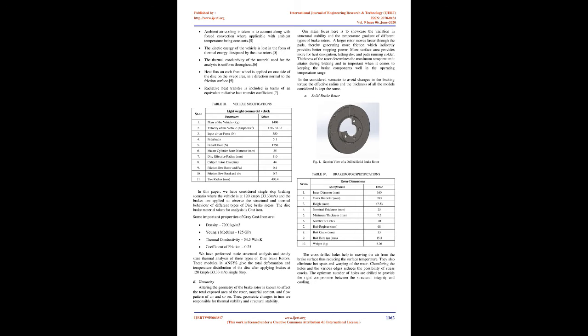Based upon braking application of the vehicle, the disc material needs to absorb and disperse a large amount of heat without braking performance being adversely affected. 1. Structural analysis and thermal analysis are a primordial stage in the study of the brake systems because the temperature determines thermo-mechanical behavior of the structure. 2. The large amount of heat produced at the pad/disc interface during emergency braking indisputably evokes non-uniform temperature distributions in the domain of the rotor.